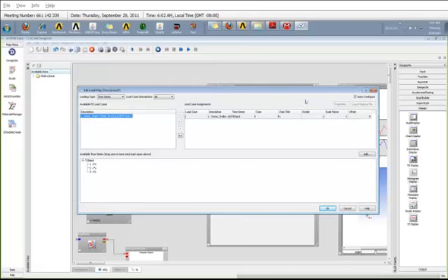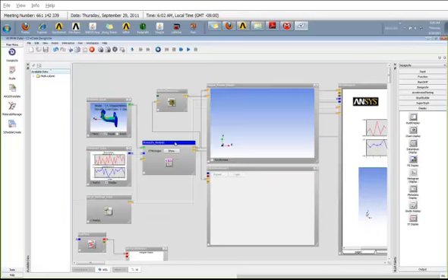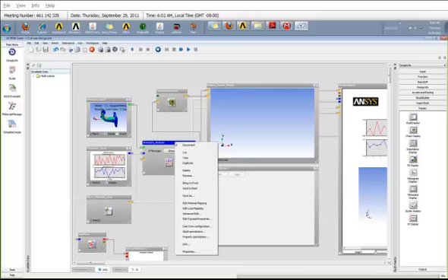But if it had chosen the wrong one, I can uncheck this auto configure and change it by dragging and dropping. Let's say this is the wrong one and I want to select FY force. I would just drag it and drop it over here, so it changes to FY. In this case, I actually want to apply FX, so I'm going to drag and drop the FX here. Also, I can set up a scale factor or offset. If you want to set up a scale factor, you can just type in that number in the table over there. Now let's give an OK to the load mapping. Let's go back to the stress life analysis. We are done with material mapping and load mapping, and I'm going to go to the advanced edit.